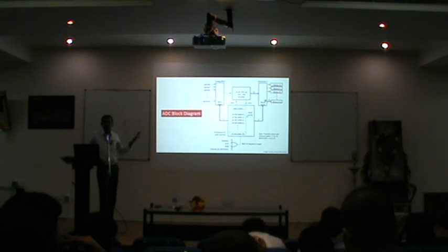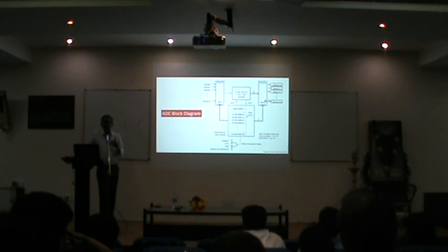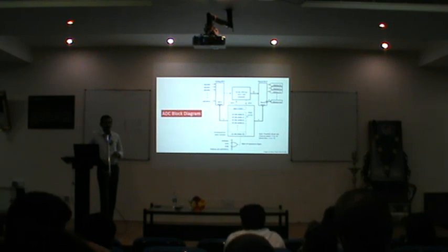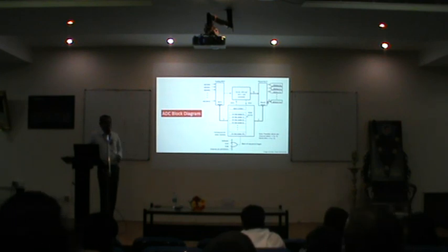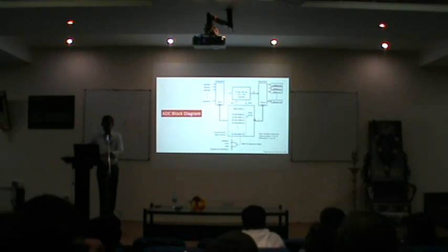It looks simple now, but when it comes to control, it is not as simple as this. Because you have to tell the ADC when to start the conversion. Then you have to wait for a predefined amount of time for the conversion to be over, sampling plus conversion time. Once this is done, you need to give some amount of time for the result to be stored in the result register. Assuming that all of these things are done, you will take that value and process it. So all these things, once again, are to be done if you want to sense any physical quantity.